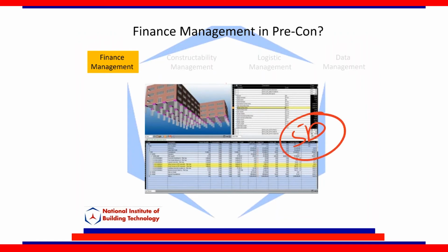Second part of this is 5D. This is what I was talking about, 5D, right? This is basically where each element has cost attached, and I used to do this way back, at least 12 years back. There was a product called D-Profiler I used, and basically the idea is to build your packages. It included all the labor forecast. It could change based on which location you're in, the labor cost, the availability of labor. And you can put all those modules and connect them to your building, so you can actually see, based on your location and on what elements and materials are going into the building, what the cost is.